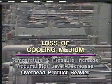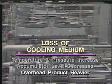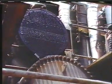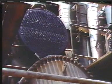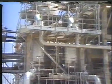A higher temperature also means that heavier material is driven up the tower, so the overhead product becomes heavier. A less severe but more common problem with overhead systems is fouling or scaling of condenser tubes. Deposits in the condenser tubes interfere with flow through the vessel and decrease the effectiveness of heat transfer from one fluid to another.